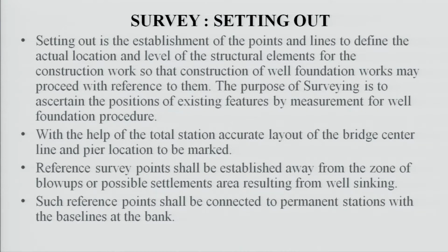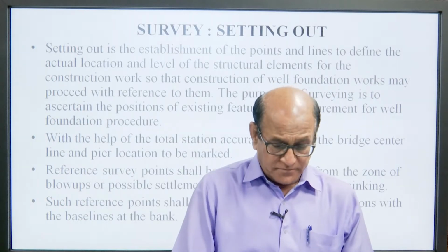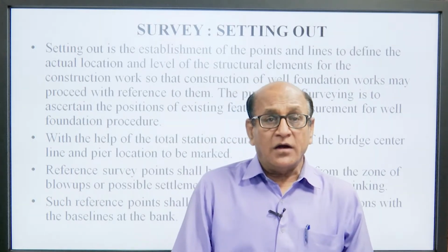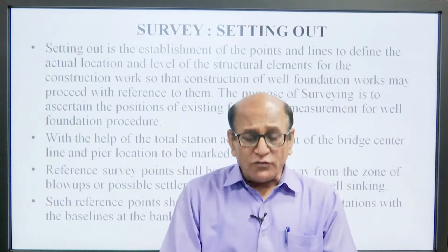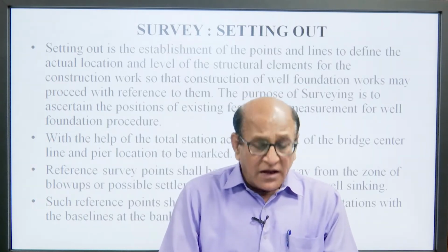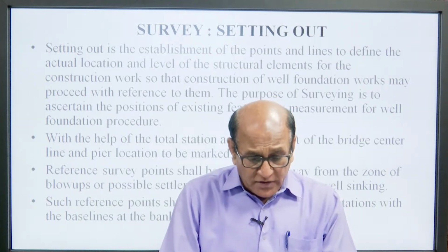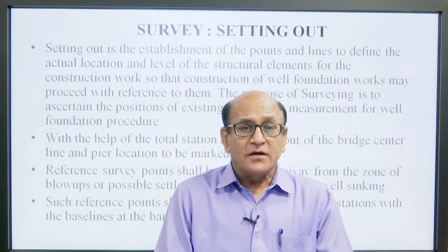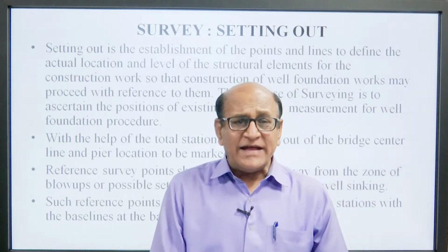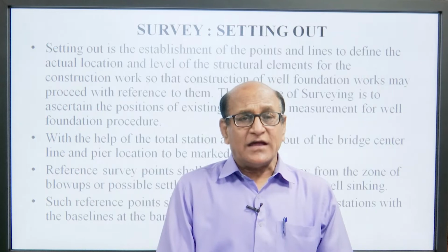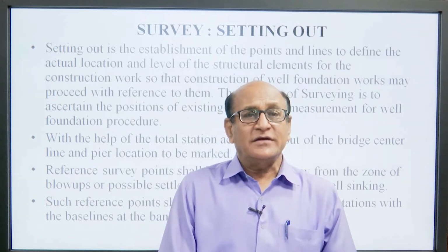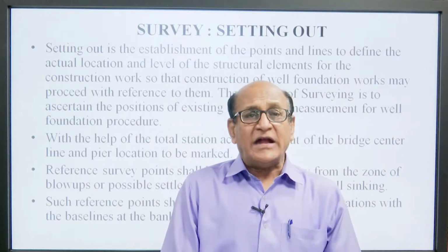The purpose of surveying is to ascertain the position of existing features by measurement for well foundation procedure. With the help of the total station, accurate layout of the bridge center line and pier location is to be marked. Today we have of course many instruments, but total station is quite an accurate and reliable instrument that we can use.